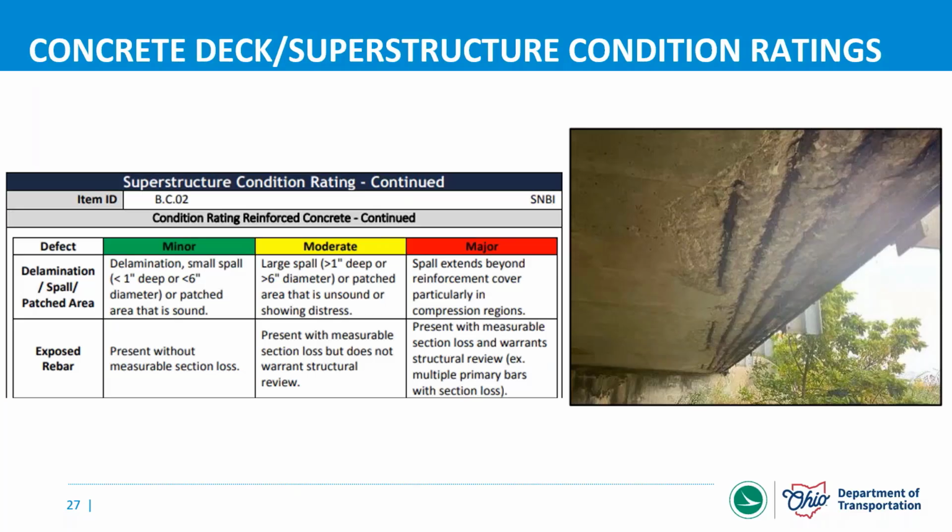scale. So that's something where I think typically we have discounted in the past, wouldn't have come lower than a 6. Now you're going to see those edge specific issues, if they are widespread, moving your bridge down to a 5. I think we can safely say, right, that this condition that we're seeing in this photo, even if it's widespread, isn't affecting the capacity of the structure until that spall creeps into where it's seeing live load closer to the edge lines. But in this case, I don't think a 4 is necessary, but we're definitely at a 5 now on situations like this instead of a 6.